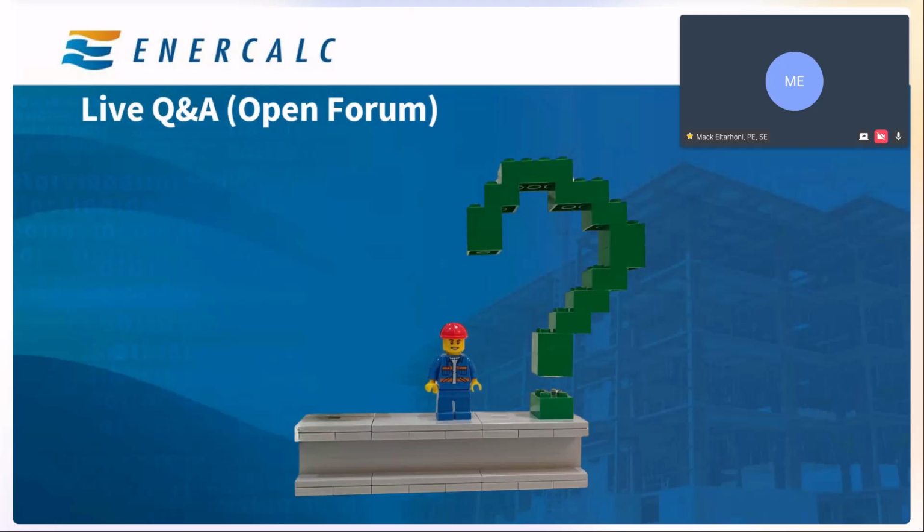I had a question earlier from Mike. When you use up to a certain span, how do you account for deflection and camber? I just want to clarify what Mac was talking about in that example. Using up to a certain span is not explicitly a feature of the multiple simple beam module. He was just talking about the way he had laid out his framing plan, and that he was characterizing his framing plan with a couple of primary controlling cases that would cover everything geometrically up to that span, engineering-wise, for his framing plan.